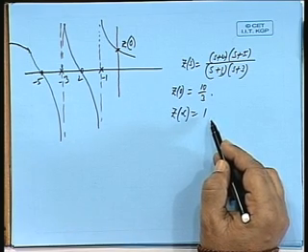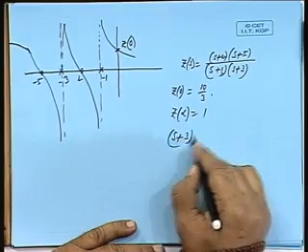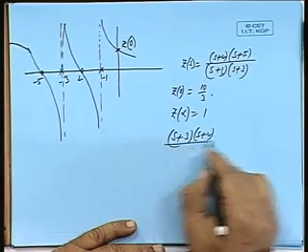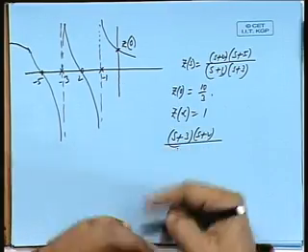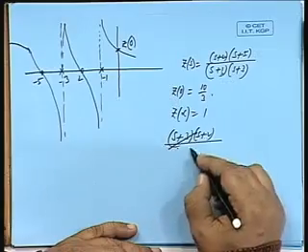It can be, under a certain situation, equal to s plus 3, s plus 2, s plus 6, s plus 1. Okay. Let us see, s plus 3 into s plus 2, then the poles and zeros are not interlacing, it will be an RLC circuit, it will not be an RC circuit.